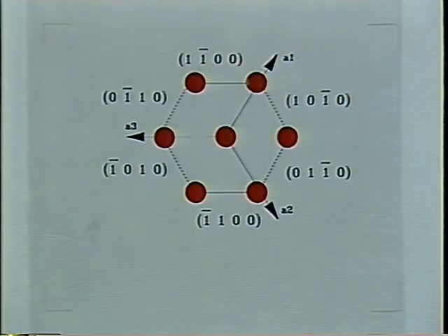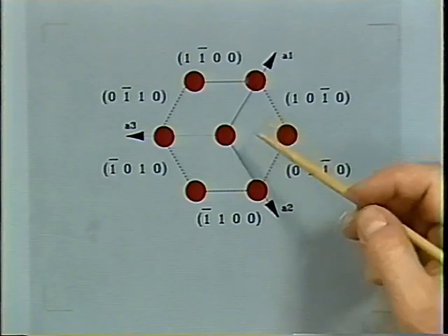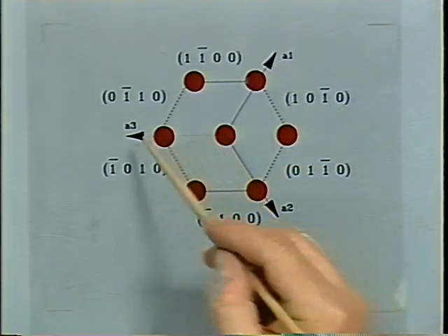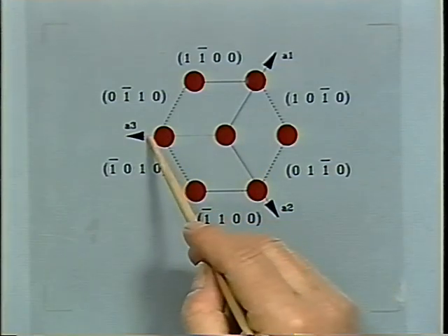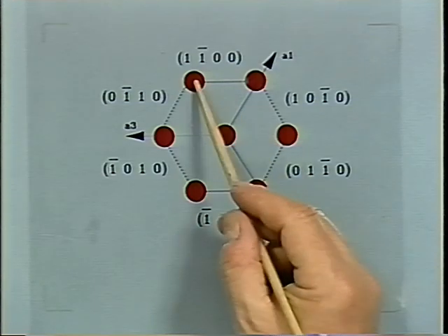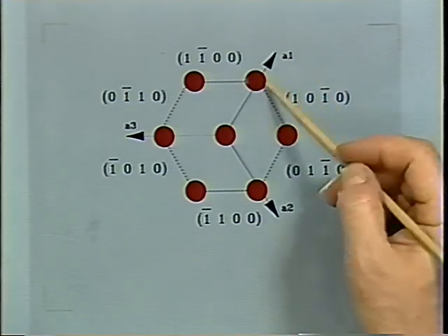Now when looking at this type of structures, the crystallography people have a special type of language, and that goes something like this. They specify planes. They give names to planes. In the first step, they choose axes of that structure. In this case, we have our axis A1, our axis A2, and our axis A3. And then they give names to planes. Like this plane here intersects the first axis at this point.